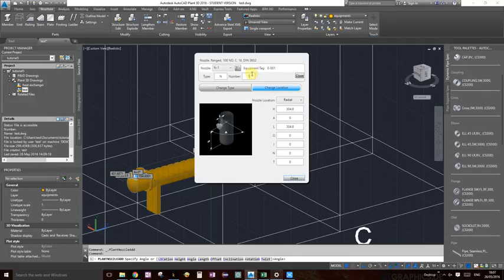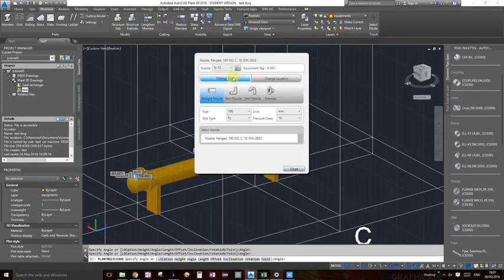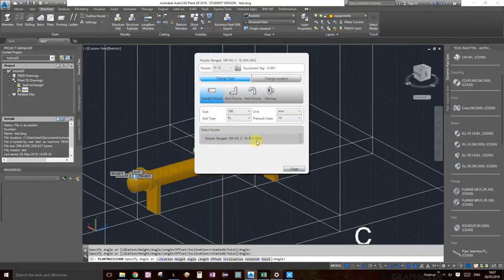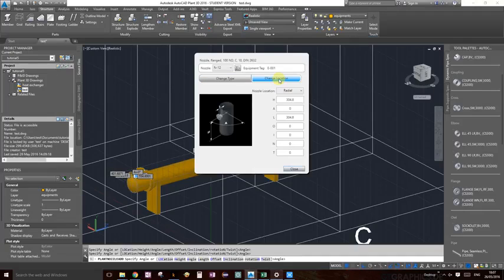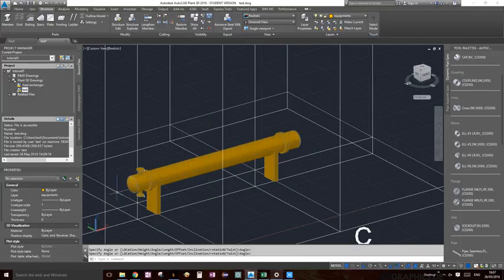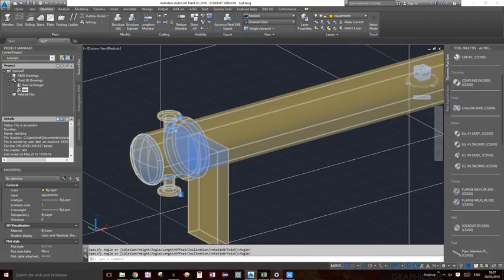We're gonna call the tag 1 2 this time. Last time we called it 1 1. And let's go back to change type. Everything is the same. Select that. Go back to change location. So now we want the height to be, was it 250? We did 250. But now our angle is going to be 270 degrees, and the length we'll keep it at 150. And that's all. Press close, and as you can see, there's a second one now.